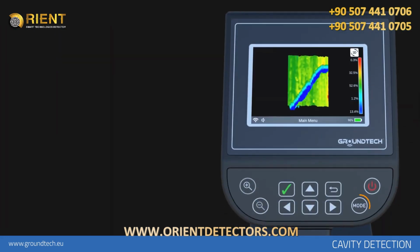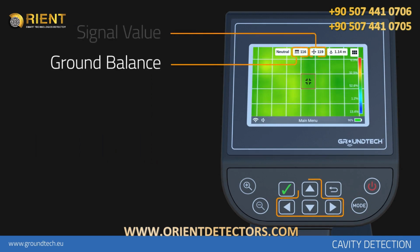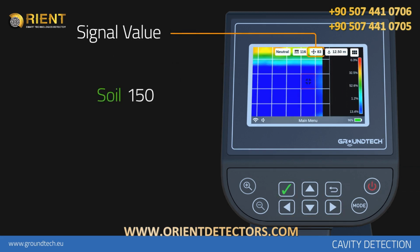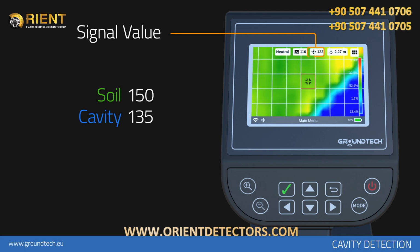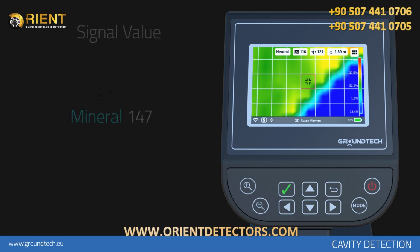In order to see this numerical value, you should switch to the Scanning Details feature in 3D Viewer function. When you go around the graph with direction buttons, you can see the soil balance value and numerical value of the selected point on the top bar. There must be a decrease of at least 15 points between the soil which is shown with green and grounds which are shown with blue. For example, if soil level is 150, then the ground should have a value of 135 to 130. If there is a difference of a few units, this data indicates ground caused by rocks or superficial soil variations.